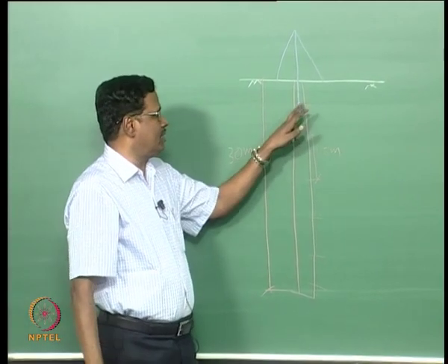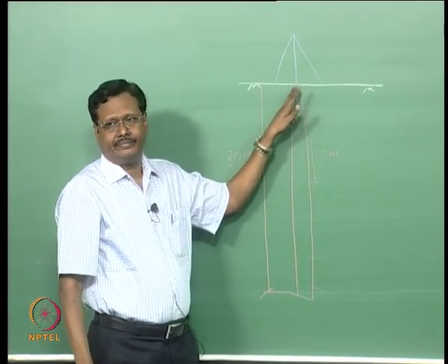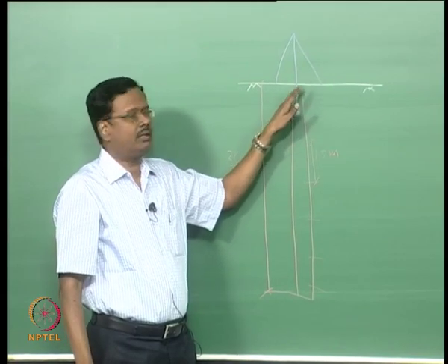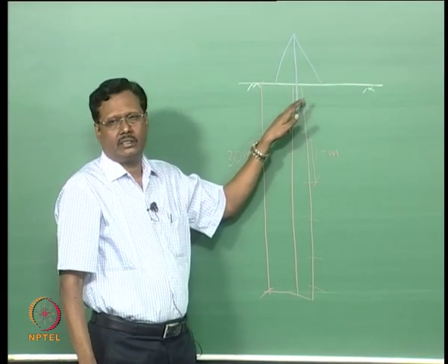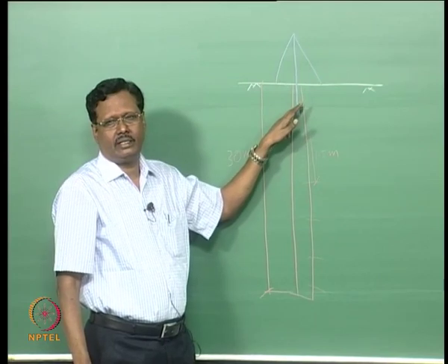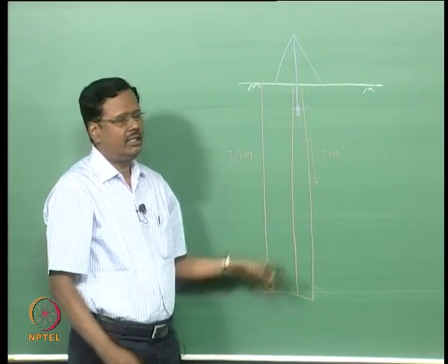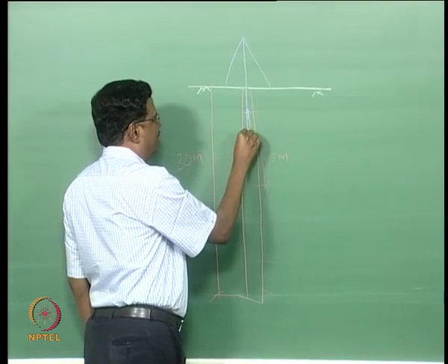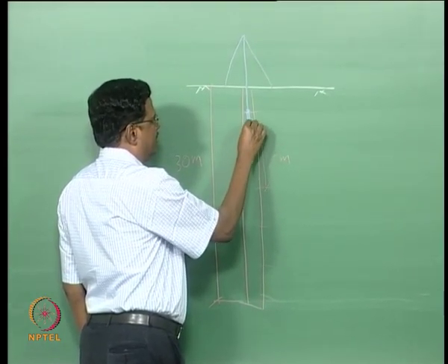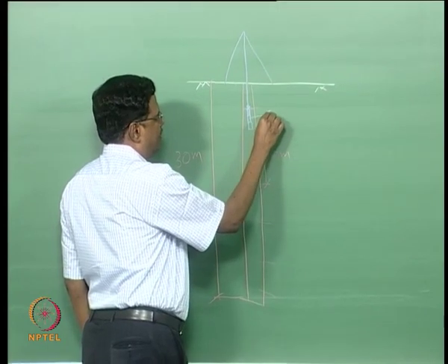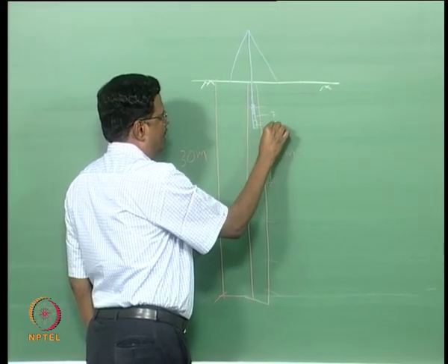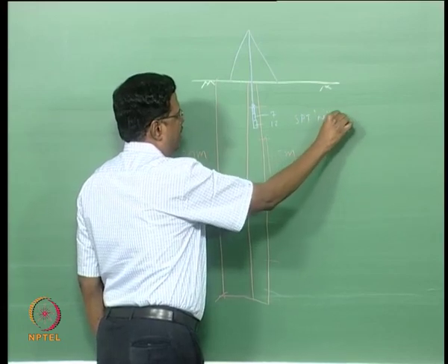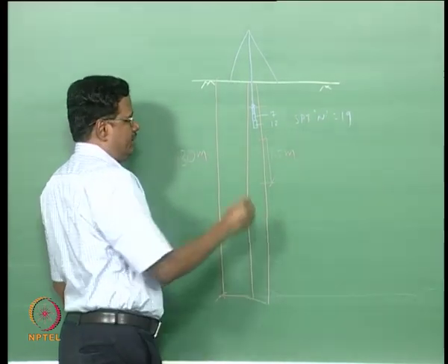Before coming to this level they will remove the soil here. So, they bore it and remove the soil, which means the soil here will be disturbed. So, they neglect the first 15 centimeter reading, then they go to the next 15 centimeters, and the next 15 centimeters. They write, let us say, about 7, then 12, so SPT N value is 19.